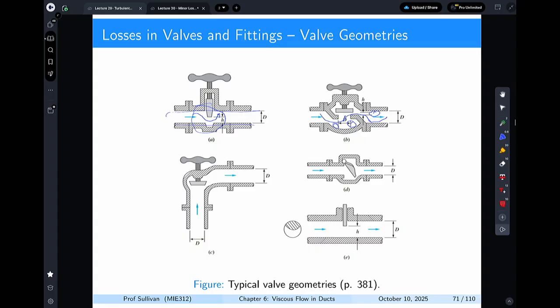It's the same thing with elbows, especially if you have something where you kind of close it off. You have an acceleration and deceleration that occurs, and acceleration and rotation of fluid that's going to happen. Same thing here, and even right here to a lesser extent. All of those cause a disturbance to the flow, and as soon as you disturb the flow, you change the pressure profile.